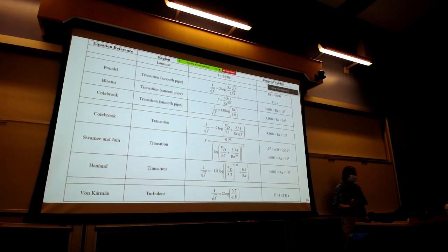So these are the equations from the previous handout, and you saw these earlier today. So for example, if you're in the transition zone, remember, we just did this problem. We know we're in the transition zone. If you hadn't already done this problem, you do not know you're in the transition zone. So if you selected one of the combinations that I'll show you on today's handout, the next thing you have to do after you get an answer is make sure you check the range of validity. If you don't do that, I would never consider your answer correct.